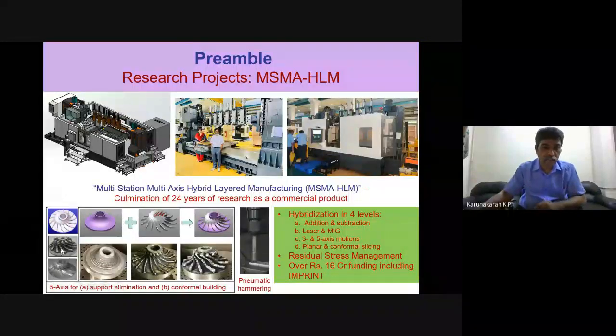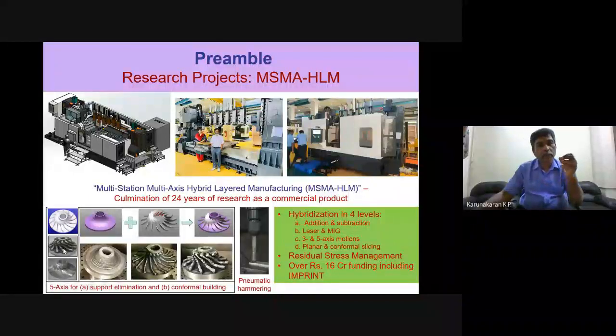mill it every time. So every time we will preheat ideally, then do the cladding, if possible outer profile by laser and inner area by MIG. So after cladding and creating the layer, it will be very rough. It will have scallop surface, height control will be poor. So we go for face milling operation. Now, I told you that we went for MIG because of our financial limitations.